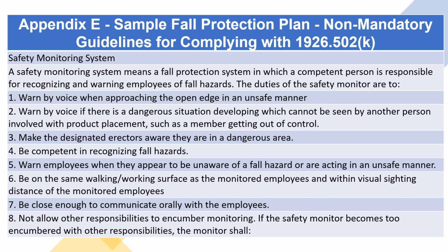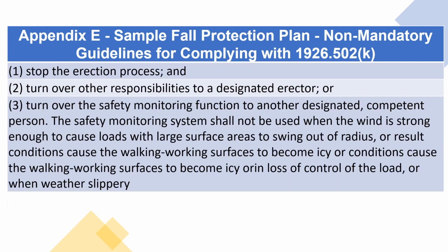If the safety monitor becomes too encumbered with other responsibilities, the monitor shall 1. Stop the erection process, and 2. Turn over other responsibilities to a designated erector, or 3. Turn over the safety monitoring function to another designated, competent person.